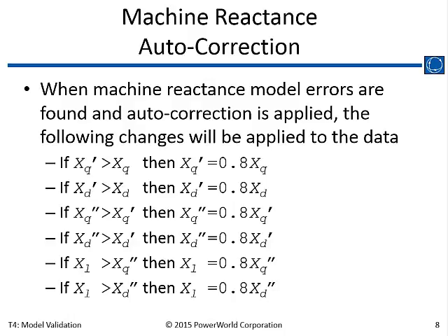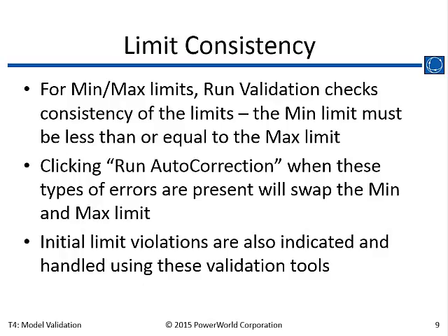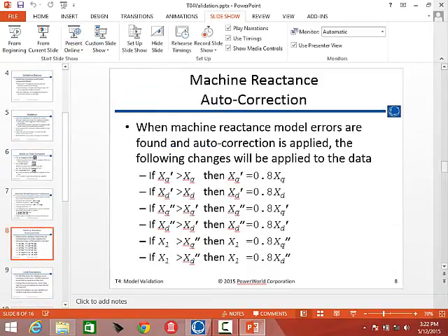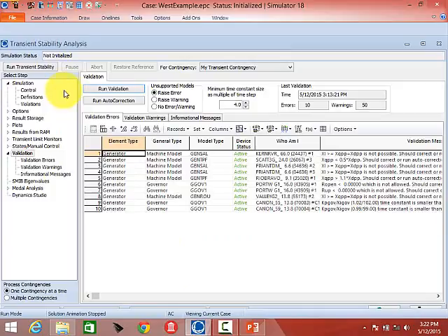So Gordon, you're saying the E files they have, basically they run the thing in PSLF, right? Yes. So they click the fixed bad data for the DYD data, and then they're supposed to export that, and that DYD file is in that case folder that starts with an E, which has the EPC format for the base case. The other folder has the binary save format, and that DYD file doesn't have this fixed bad data applied.